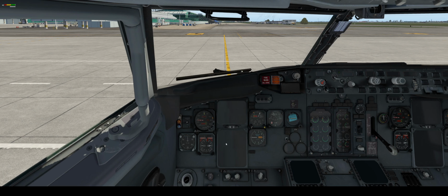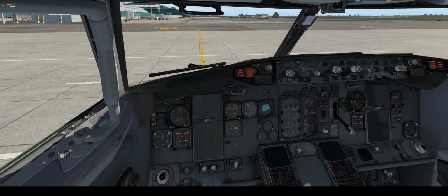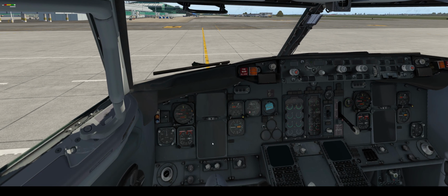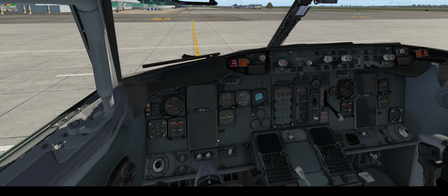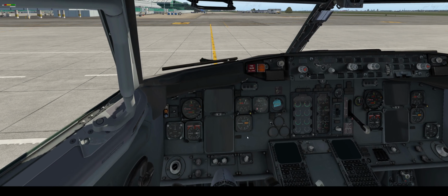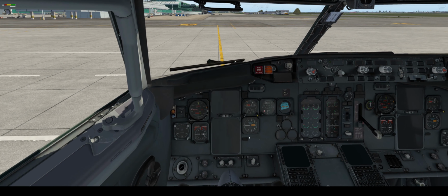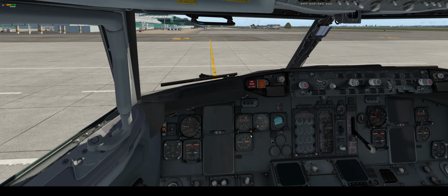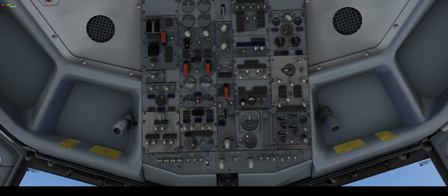The most common failure is that the CRT is completely broken, so you have no checklist on the QRH for this. In this case, after landing, somebody goes to the E&E compartment and resets it, and it will work again.